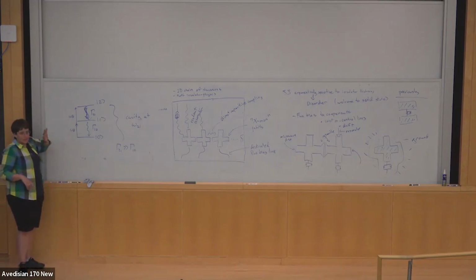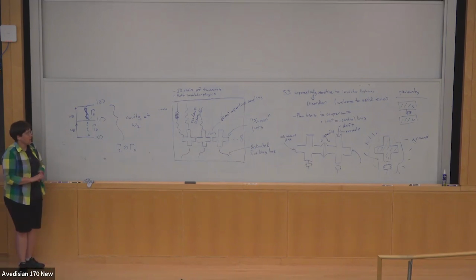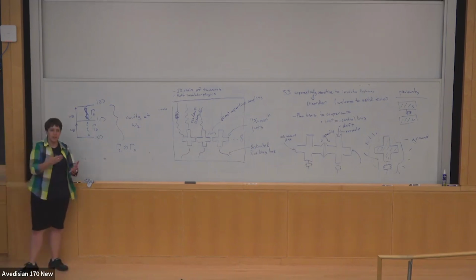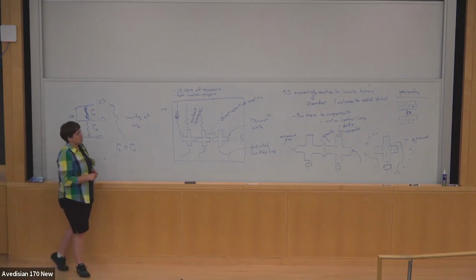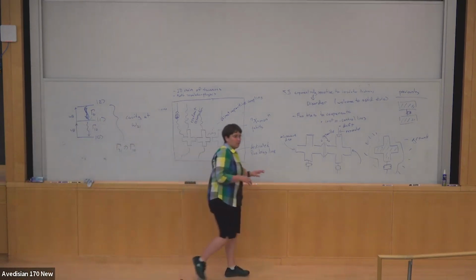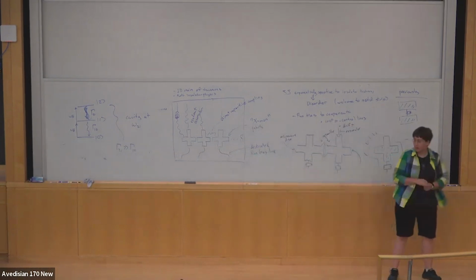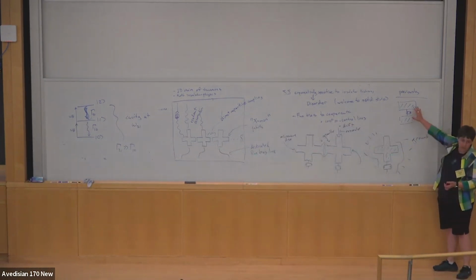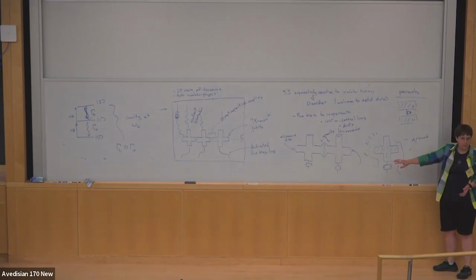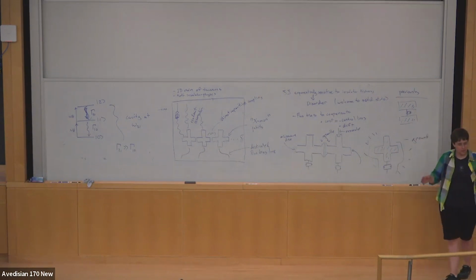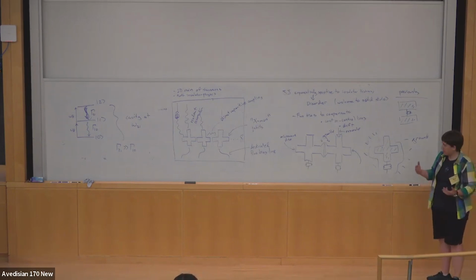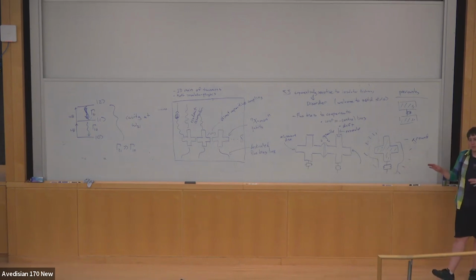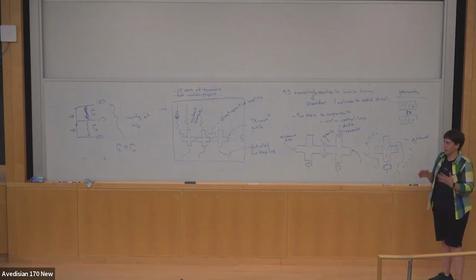But one of the big advantages you have is twofold. One, there are a lot of different circuits that give you the same Hamiltonian, so you have a huge amount of freedom to decide how to implement a circuit, depending on what you care about. Do you want to go for the double-sided transmon, or the Xmon? They have a different footprint and couple differently to different things. There are also a lot of different kinds of cavity you could use, not just the coplanar waveguide one that I drew. That gives you a lot of ways to optimize depending on what your biggest enemy is.